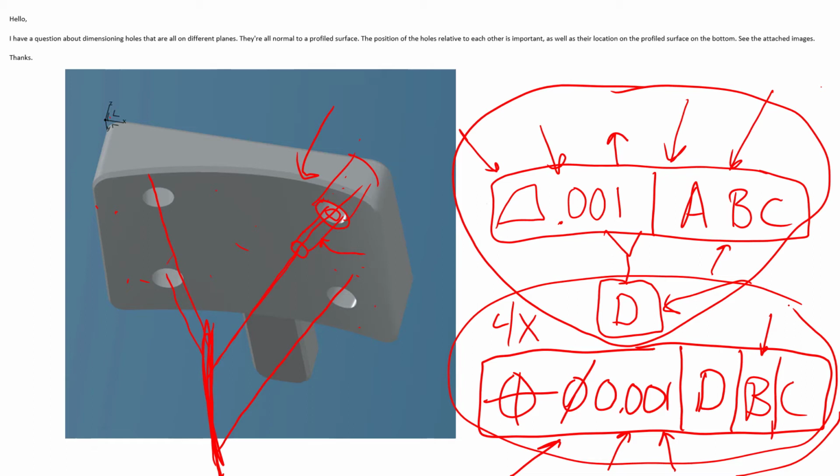So it is simple. But just understand that if you're sending this to a machine shop, to a place that may not have the way to set up virtual axes like this, you may want to reconsider a different inspection method or allow them to use datums A, B, and C and give them some sort of reference basic angle to do their inspection from.